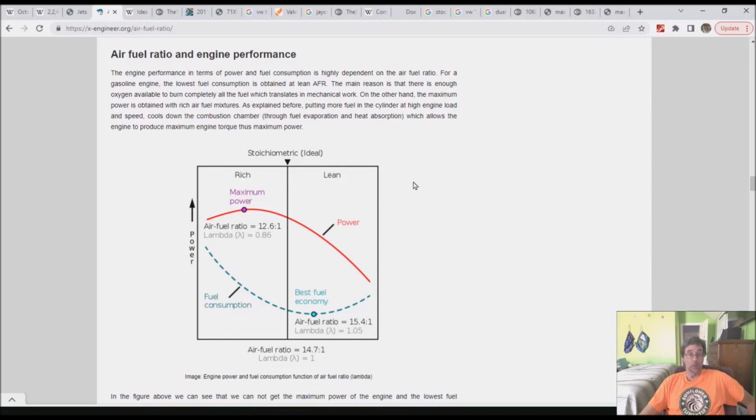So that white-haired old fart didn't know what he was talking about. He was in the ballpark. In addition to that, we've also got an air fuel ratio that tells us efficiency of 15.4. Usually it's going to be a little bit more down this side. You've got to go a little bit further this direction to hit peak efficiency. We don't have the best combustion chambers in the world, so you go down this direction a little bit further for our motors. So why would this produce a better, cooler running motor?